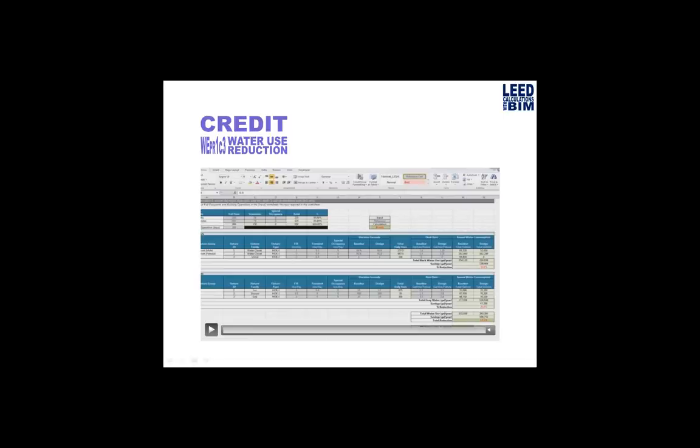Right. Well, you have your high performance fixtures, and there's type, right? So you could put that information in the type properties. So every time that fixture is placed, it's accounted for. Because the schedule is not pulling out each individual fixture; it's pulling out the fixture user group, if you're using type settings, not instance settings. So even if it's a large building with thousands of fixtures, you may have just a handful of types that you can quickly validate the settings. Right.